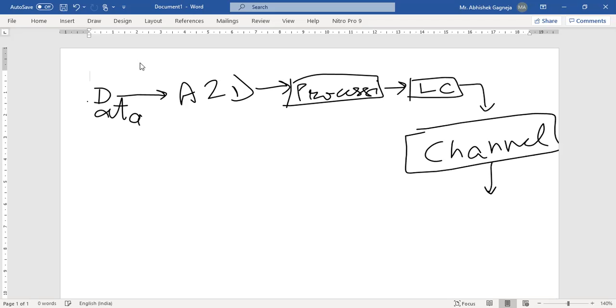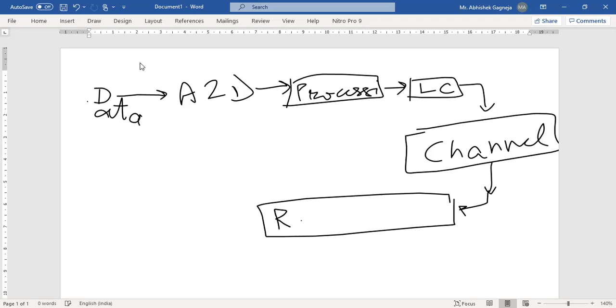So the main issue where the intersymbol interference logic is going to happen is the channel. What is happening in the channel, and why is it that we get interference between the transmitted symbols is the main crux of the question. So normally what would happen is that there will be a sequence of receiving structure. That receiver will be a filter or things like that.